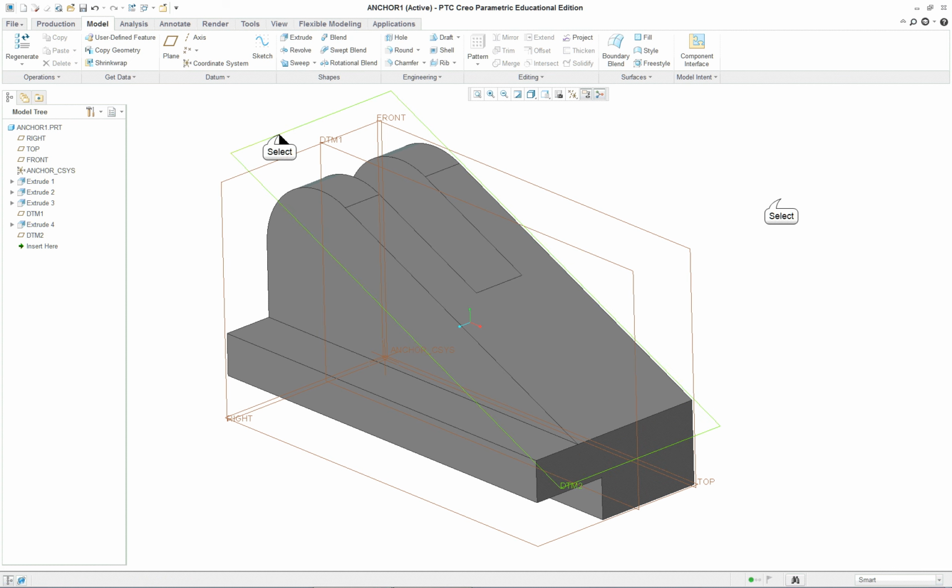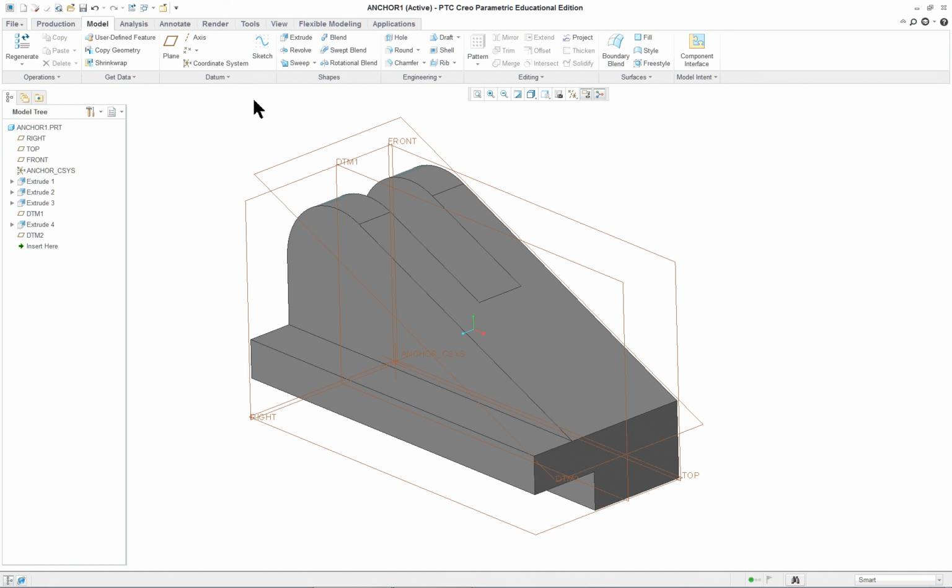So I've got an angle datum plane through there. So now I've got 5 datum planes. Now, this is not following exactly what's in the book, but it is for the geometry. Later we'll talk about the datum planes and the geometric tolerancing, etc. So we do also want a datum axis down the middle of this arc.